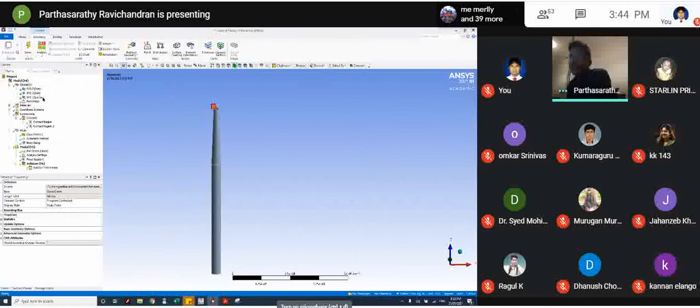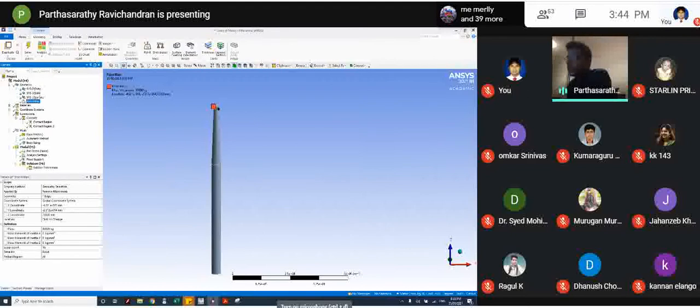It would ask you what coordinate system this remote mass has to be in, and then you can define, as we said, that the turbine is sitting at a height of 74, 73, 72 meters. So the center of the nacelle is somewhere 1 meter or 1.5 meters above that. That's how you define this location.